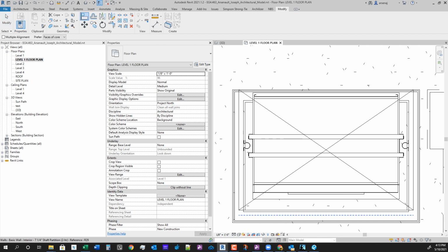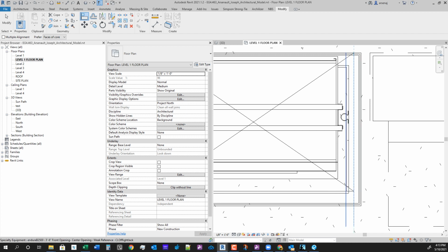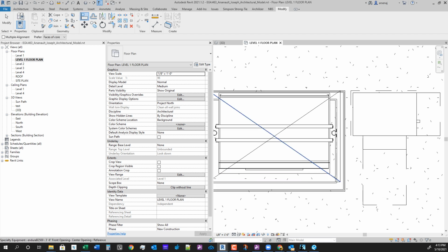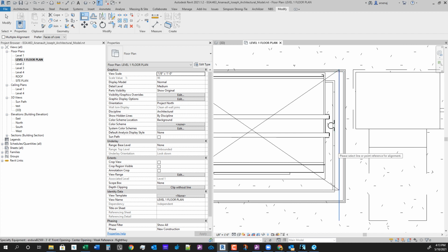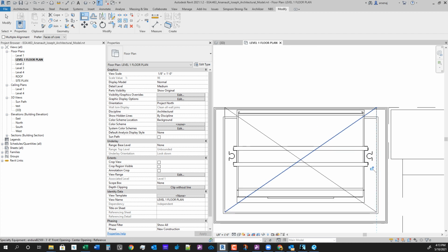So you can select that line from the elevator family and then align our walls to it. Oops, undo, accidentally aligned something else. AL to align, pick the elevator boundaries, and then align our walls.